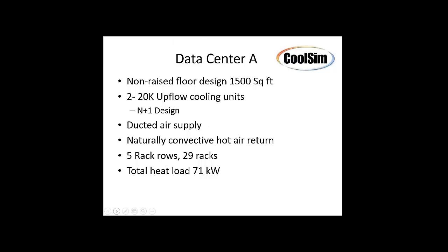So the first data center we're going to look at is a fairly small one, 1,500 square feet. It's got two 20,000 CFM upflow cooling units. It's an N+1 design, so it's designed to run with just 20, and that's how we'll be modeling. This is a naturally convective hot air return system. It's only a 71 kW data center.